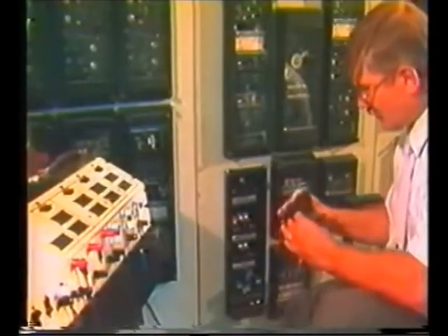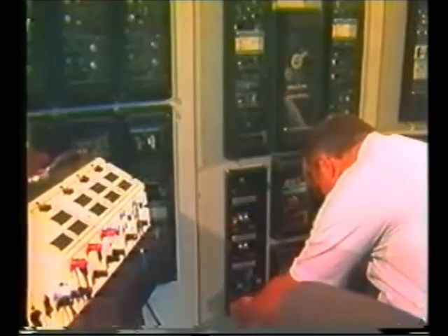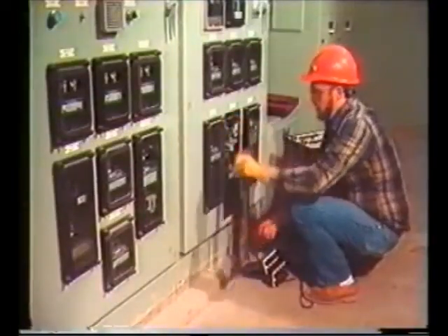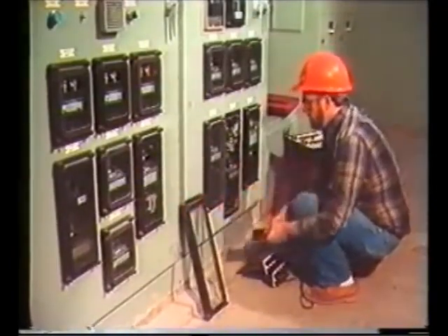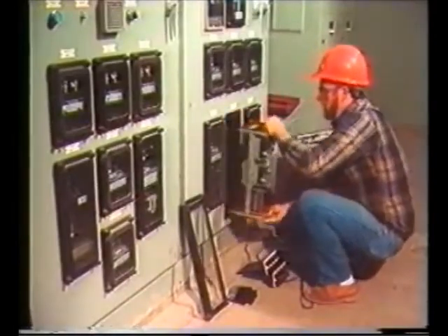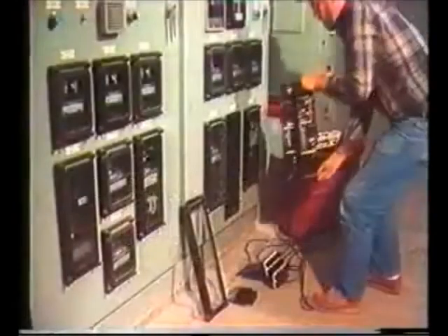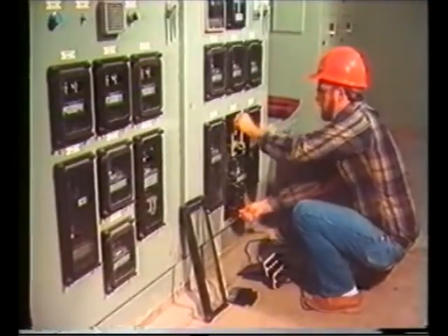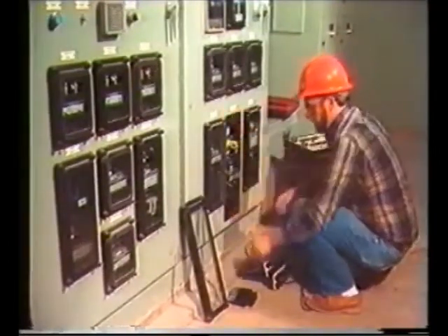Relays are often tested in place so that the total circuitry can be checked as well. Alternatively, they can be removed from the casing and placed on the test bench for test and calibration. When you remove a relay from its case on the panel, you can see the base contacts. These are providing input from the VTs and CTs or other sources to the relay sensing circuit, and also are providing a continuity of the breaker trip circuit.